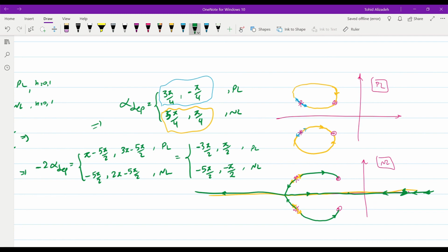At some point, it will meet the branch coming from here. They will depart the real axis, and then they will arrive at the zeros, because you should remember that we have no asymptotes in this case. But those are details that we are not interested in for this problem. We were supposed to find the angle of departure from the poles, and we are done with that.